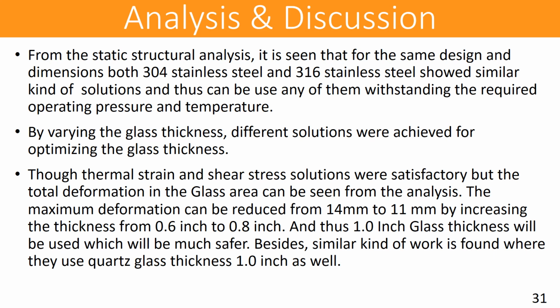Besides, similar work is found where they use quartz glass of 1 inch thickness as well for their experimental setup, and they have those window selections as well. They were operating their experiment at 6.7 bar, but it can withstand up to 15 bar. So from the reference of their work, we are going with this.